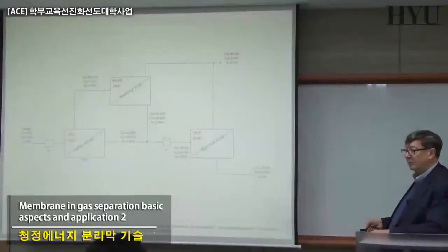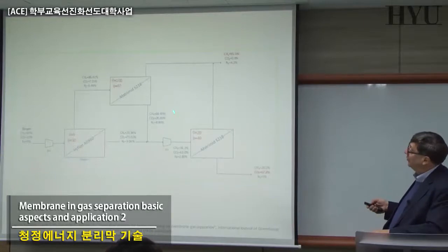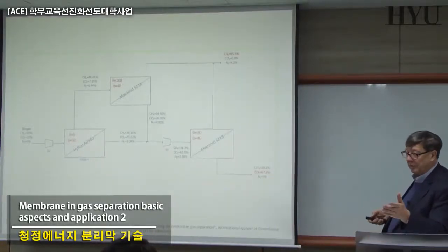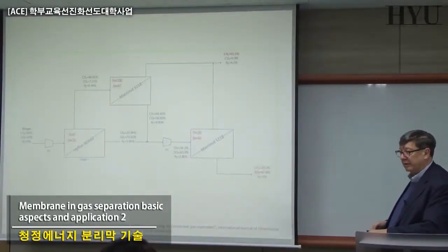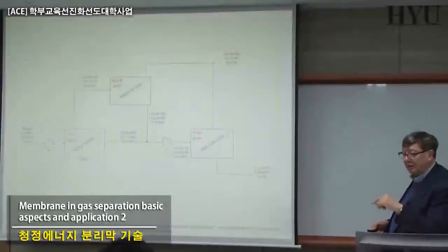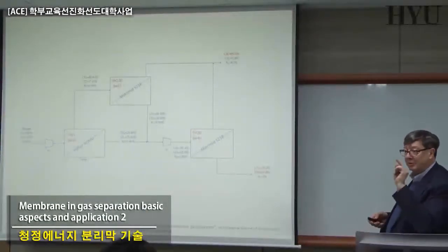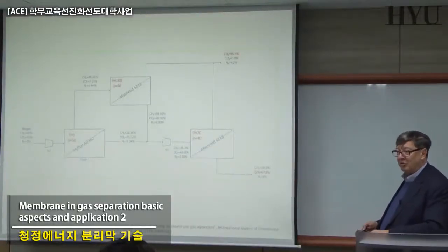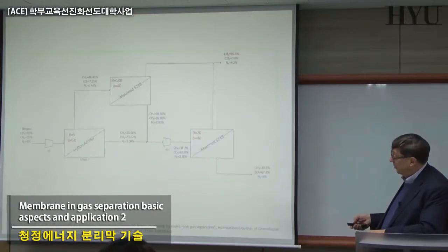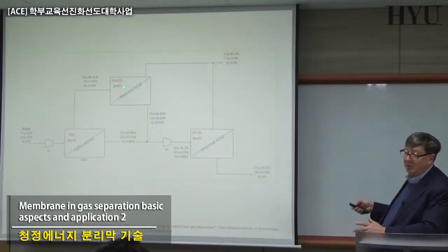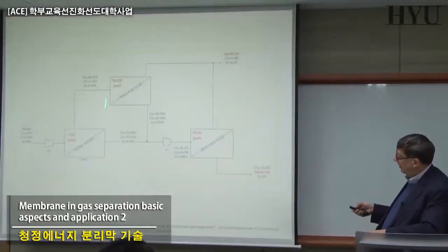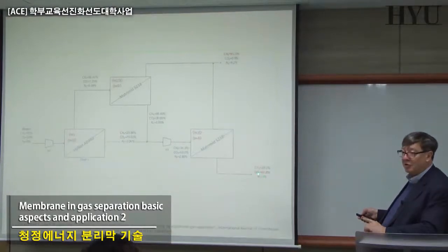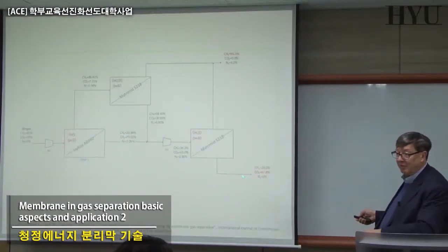Just to show you that you can do the same analysis in perspective. This is still to be submitted, but now we separate the case which is much more realistic today, CO2 methane, with the existing membranes, including the new ones people are studying in different labs, including eventually Nanyang University and others, because these have also been tested. You can see here that with some polyimide, which are interesting membranes, 3 stages are necessary for the level of purification and separation necessary for this kind of application.